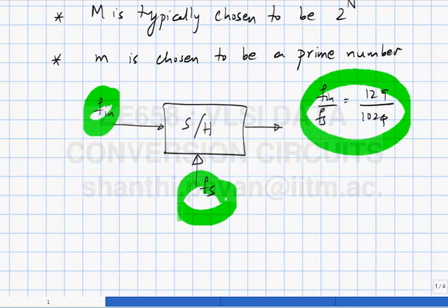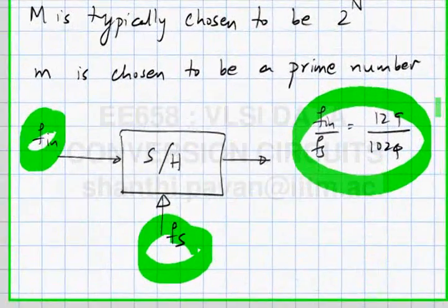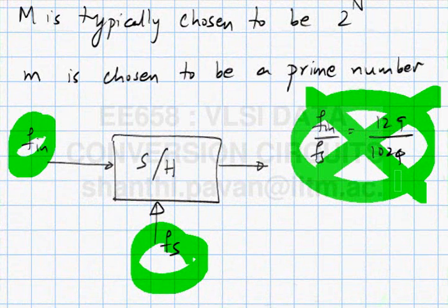But even if it were the same to begin with, over time there is noise and temperature changes daily and so on. These things all affect the frequency of oscillation of these two independent sources, correct? And they will not be in sync after a period of time. The same thing can be expected for any two independent clock sources. So even if this was somehow enforced at the beginning, as time builds up, the two of them will eventually get out of sync, so that this relationship will not be valid anymore.